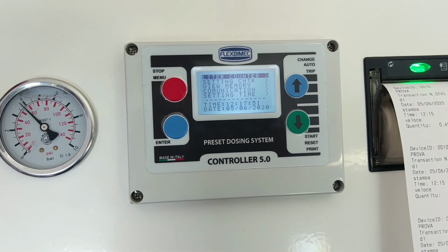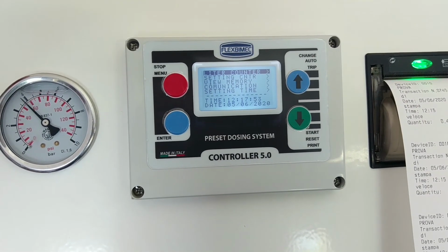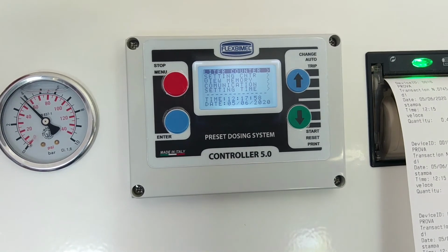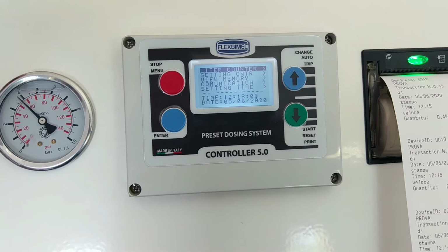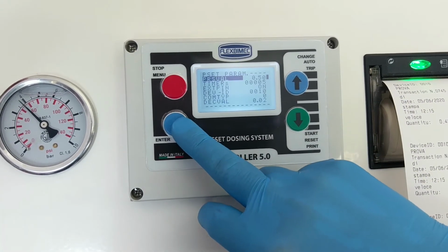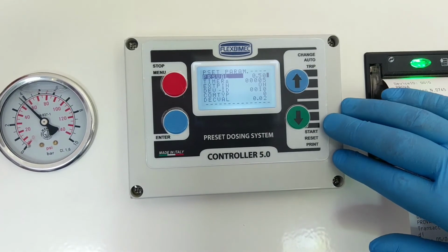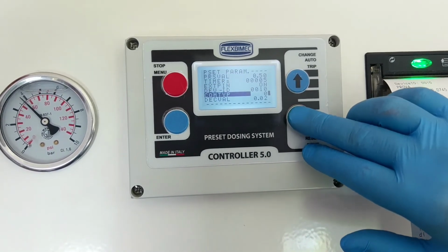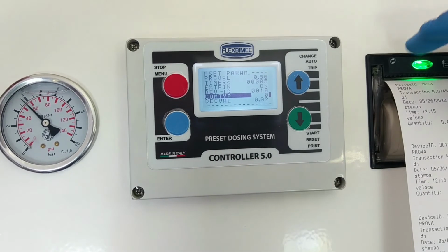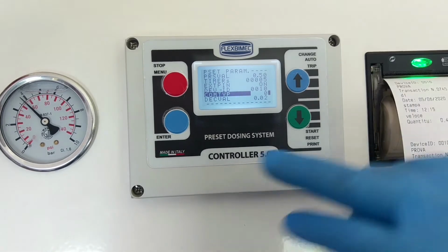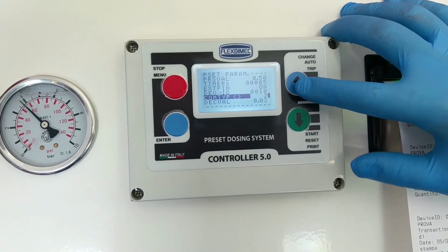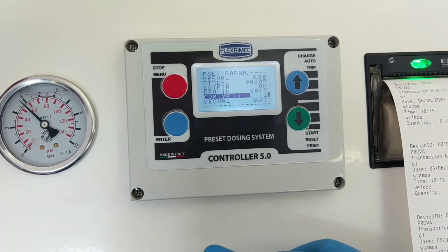The device can be connected to a software installed in a PC to be able to replicate the settings from the display of the device. To do so, I'll have to go on the menu settings and change the route of communication from the record card. I then select the item and modify the parameter. In this case, it's on 0, which indicates printing directly from the device. We should set it on 2 to be able to read from a PC through USB or Bluetooth.